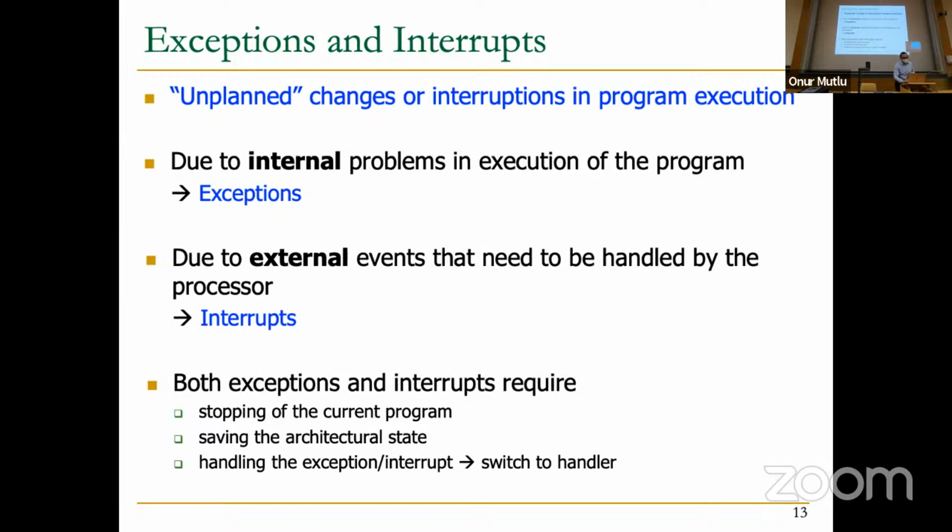Okay, interrupts are actually very similar. So a keyboard interrupt comes in. Here, you basically go to a handler that executes code to get the data out of the keyboard and puts it into an appropriate place that it needs to go to so that the system actually does something with it, right? Okay, and in the end, if possible and makes sense, you need to return back to the program execution because you interrupted, stopped the program, you handle the exception or interrupt, and then you put the program back on the processor and continue executing from where you interrupted the program.